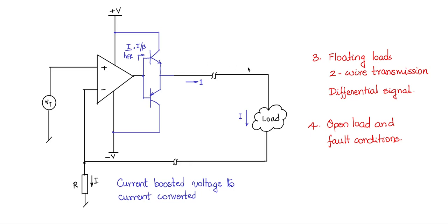So, this important consideration has to be taken into account so that when Vt is 0, we want to have 4 milliamps to flow in the remote load, and when Vt is max, 20 milliamps to flow. And when the remote load current becomes 0, then I know that this has gone bad. So this is the 4 to 20 milliamp standard. So that is how it has evolved.